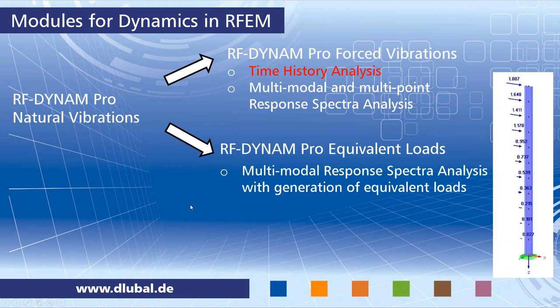And then we have the module RF-Dynam Pro Equivalent Loads. This contains a multimodal response spectra analysis. It is again the same, but here you get equivalent loads calculated and exported into load cases, which you can then use in RFEM, like in this little example here. I won't go into detail on this equivalent load module.